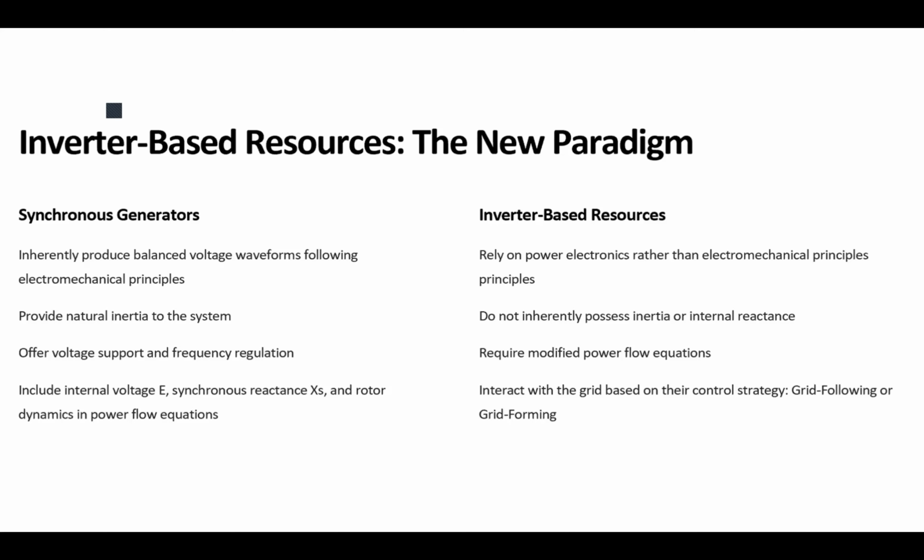Another difference between inverter-based resources and rotary machine resources is that they have to rely purely on the control system to address the load's demand, either active power or reactive power.